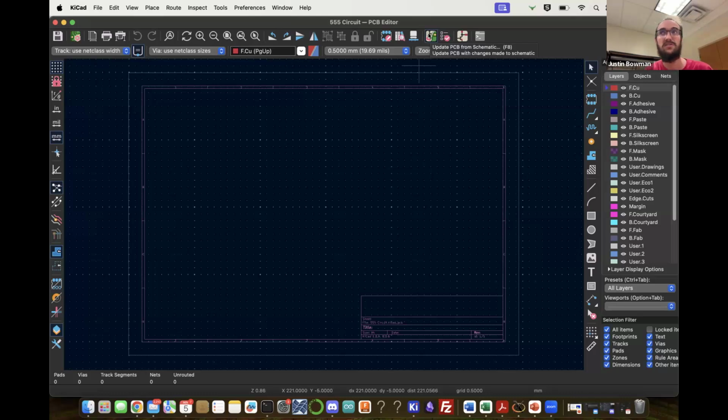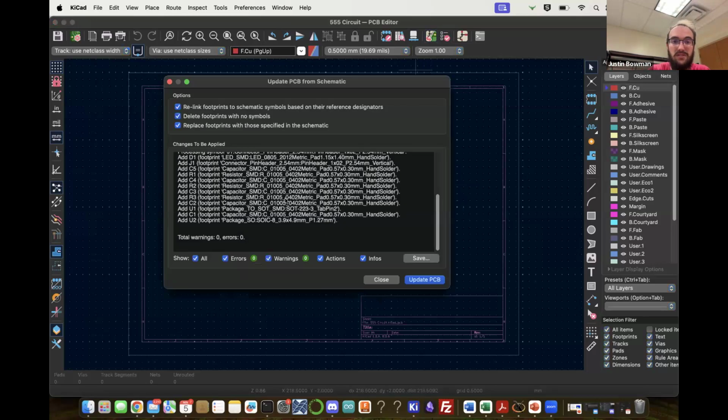And if we make changes to the schematic, all we have to do is press this button, update PCB, and it will make changes to our actual PCB layout, adding new components, changing the connections, and all of that. So it's very useful to start with the project like we did in order to get this button to appear and allow us to do this.